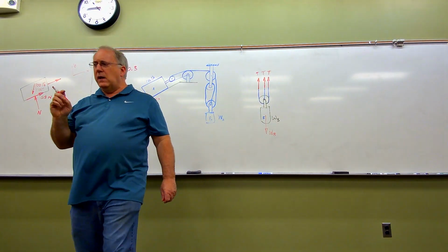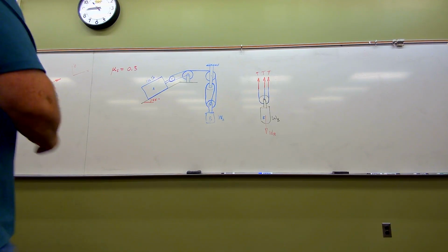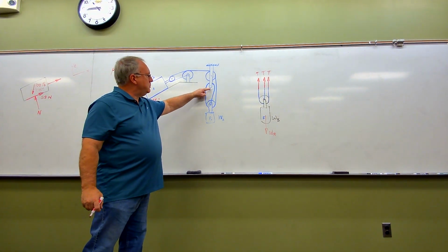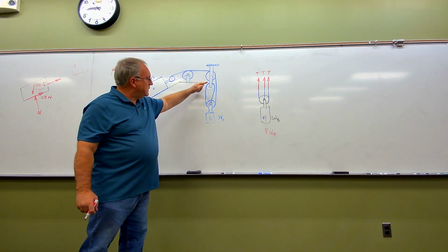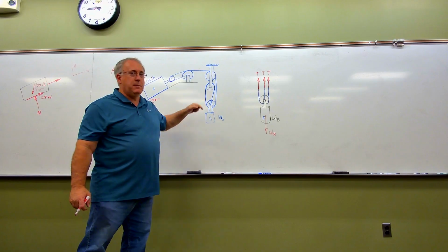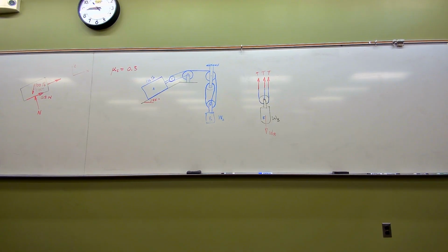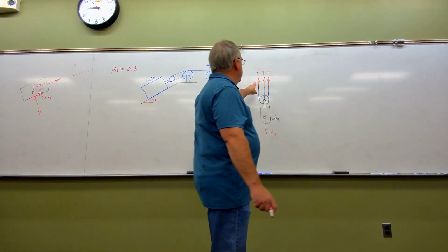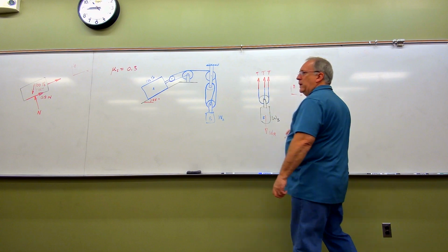Folks, there is a very important assumption we're making right here. This problem doesn't say a thing about it, but we have to understand something. Even though the original diagram shows that the diameter of this pulley here is apparently smaller than this diameter up here, which causes there to be a slight angle on this cable right here, we have to understand that without any dimensions, we are going to assume that that's negligible, all right? That means that we're going to assume that every one of these tensions are purely y-directional forces.